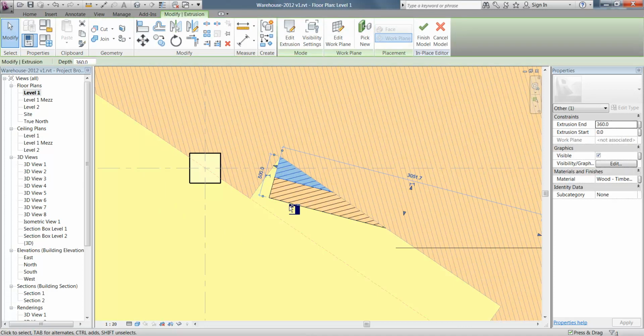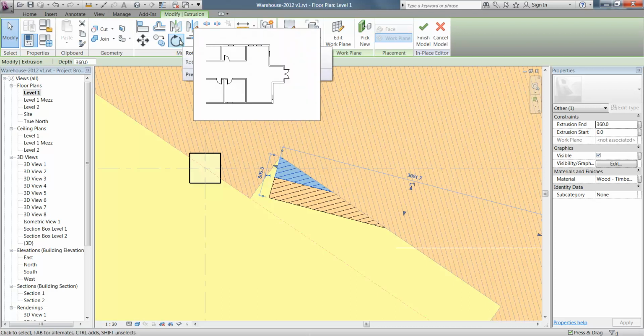Okay, so just like I did there, I needed to line the corner of the stair up with the corner of my floor accurately. So I needed to snap onto that base point. That's why you use the move tool. Same with the copy tool. And so you've got a lot of those basic things. If you're comfortable using AutoCAD, they'll be second nature, but it's easier to miss them in Revit because they try and make it so intuitive. You miss a lot of the essential tools.